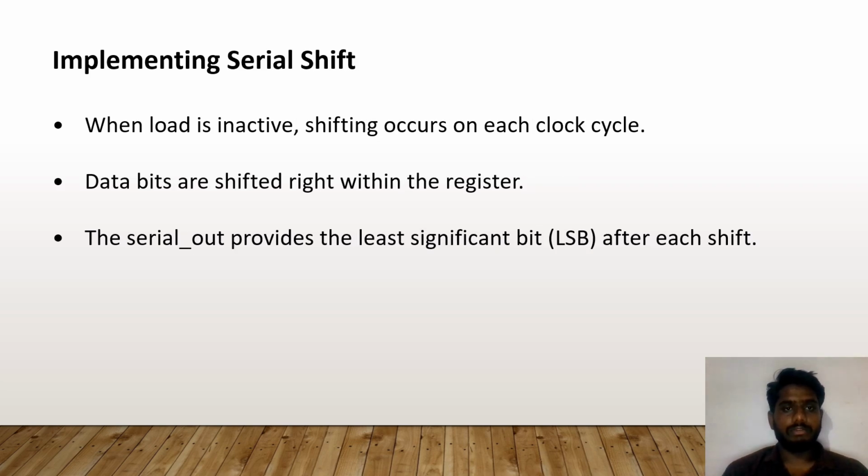Implementing serial shift. When load is inactive, shifting occurs on each clock cycle. Data bits are shifted right within the register. The serial output provides the least significant bit after each shift.